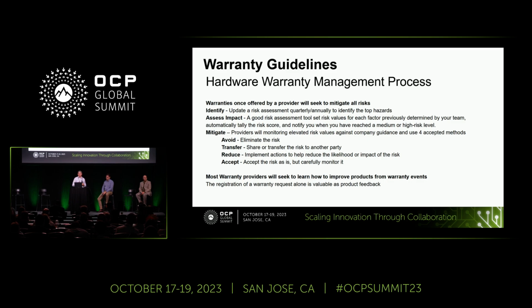Once the warranty is offered, everybody wants to reduce risk. Now, we all know that there's a different set of risks in the tank depending on what you've picked in that recipe, and those risks need to be mitigated. Mitigation measures are, hey, keep it under this flow rate, or keep it under this temperature rate, or keep it within this temperature range. There's a bunch of ways to do that, and typically that will be spelled out in the warranty.